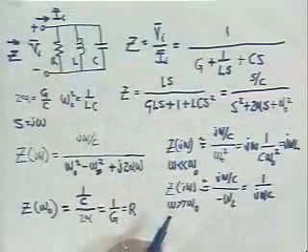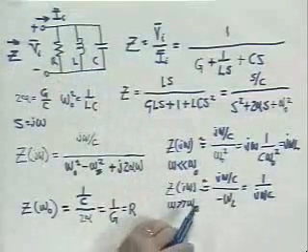What is happening is that the admittance of the capacitor, which varies like j omega C, exactly cancels the admittance of the inductor, which varies like 1 over j omega L. And if you set up that equation, evaluating the magnitudes of those admittances, you find that at frequency omega naught, the two admittances exactly cancel. This does not mean that there is no current flow in the inductor and the capacitor.